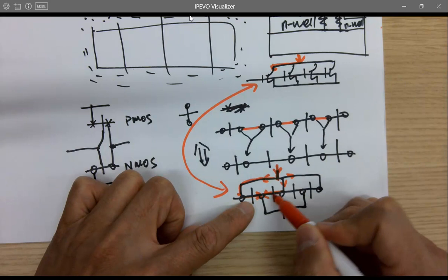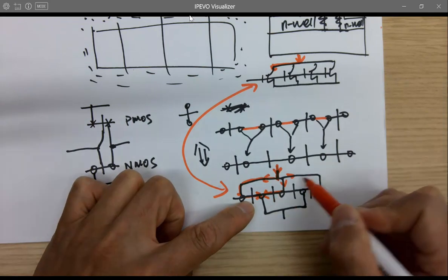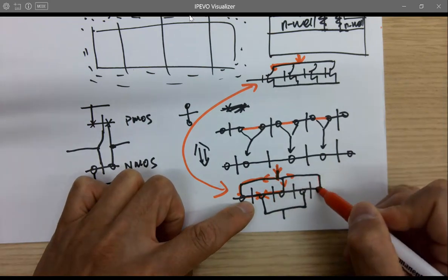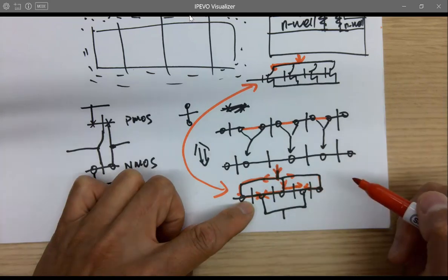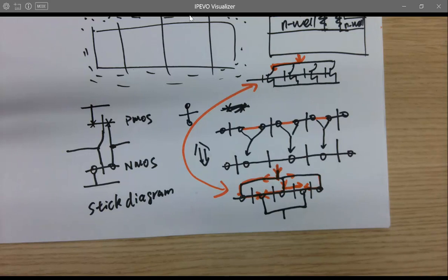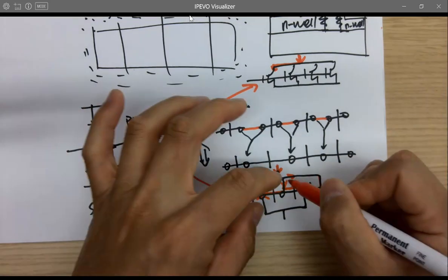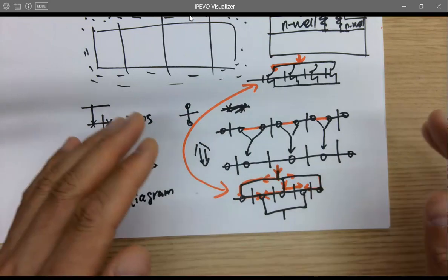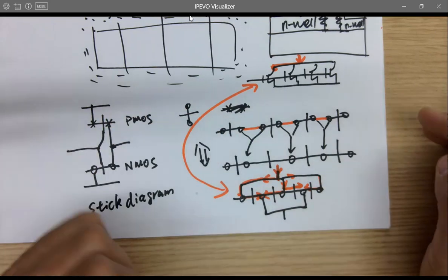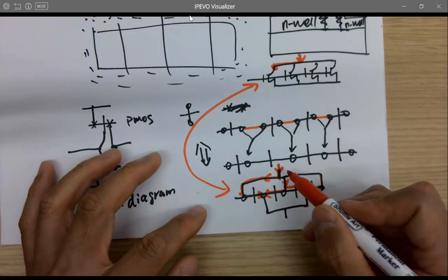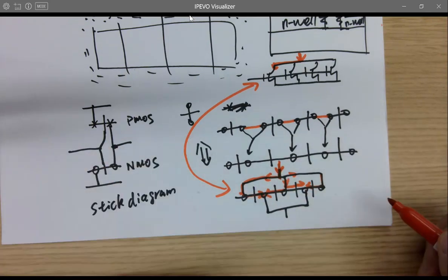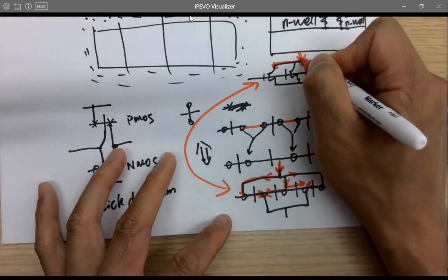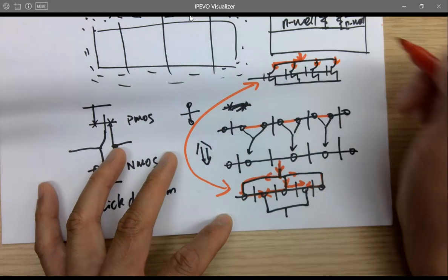So 2 transistors in parallel already. Same thing to the other side. One more transistor and one more transistor. So it flows across the gate, which means it flows through the channel as one of the branches. And these four are in the same hierarchy, the same level, same layer, same branch. So basically you have one current being split in four equivalent currents. Same thing, 1, 2, 3, 4.